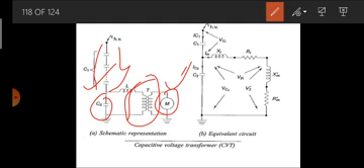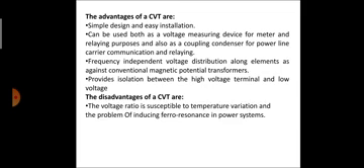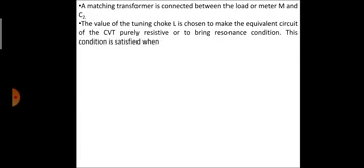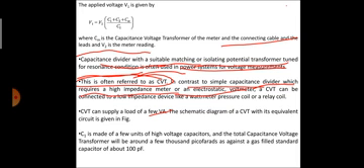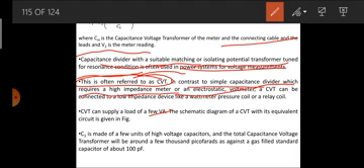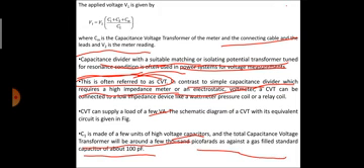Now the ratio of this transformer is chosen. You can see C1 is made up of a few units of high voltage capacitors, and the total capacitance will be around a few thousand picofarads, as against a gas filled standard capacitor of about 100 picofarad.